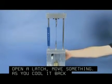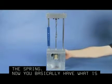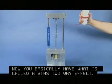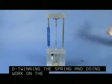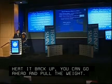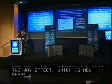So now you basically have what's called a biased two-way effect. You're going to have the weight de-twinning the spring and doing work on the spring, but then when you heat it back up, you can go ahead and pull the weight, and so you have basically a biased two-way effect, which is how shape memory alloys are usually used. If I can have the next slide, please.